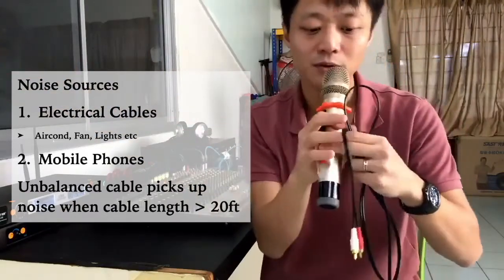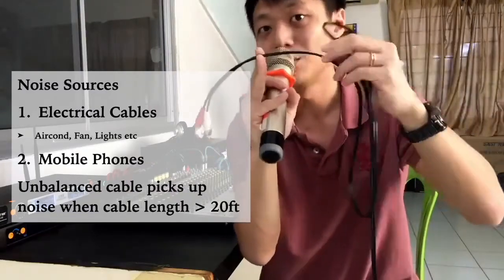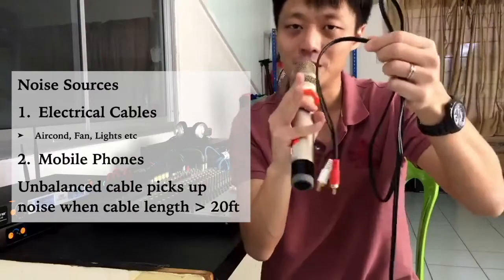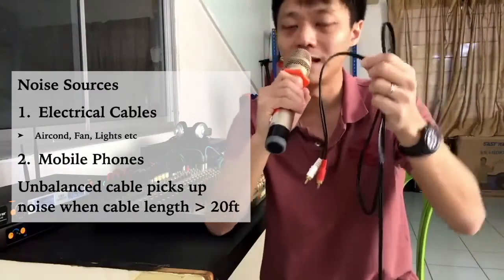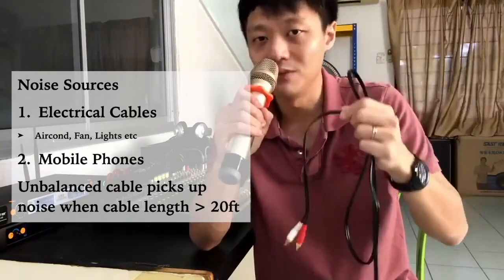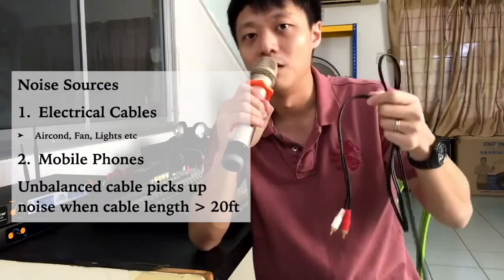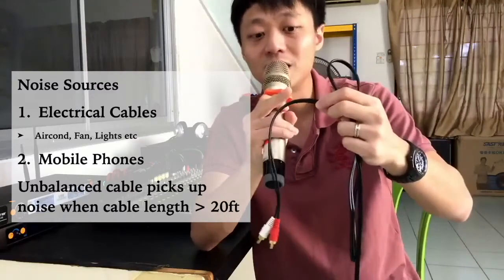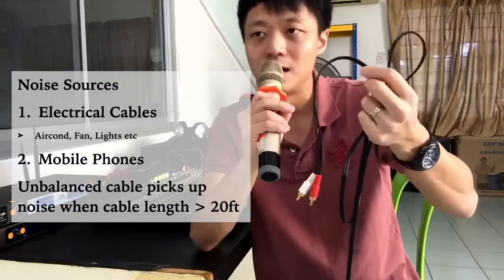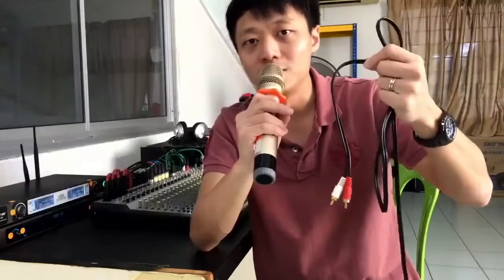Okay, so all these electrical cables cause some electromagnetic interference down here, so it will eventually pick up some noise in this cable because it's unbalanced. Unbalanced signals cannot travel more than 20 feet without picking up some noise. Noise can also come from, for example, your mobile phones. When you put your mobile phone near these kinds of cables which carry unbalanced signal, you will eventually hear some interference, like a buzzing sound in your audio.